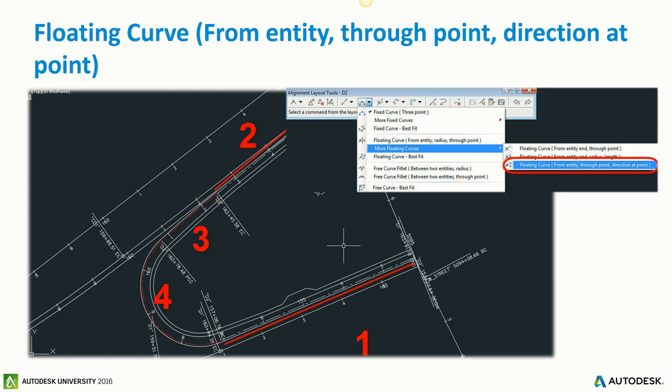In fact, the point of tangency where that line is going to be is known because there's a bridge over there, and based on the highway design manual, Caltrans design standards, it has to be a certain distance behind that. So you know exactly where that point is going to be. Okay? I'm telling you these criteria because they're going to be important when I start doing the actual alignment. Then those two are good.